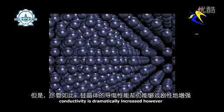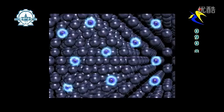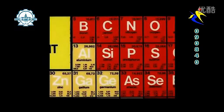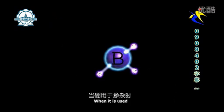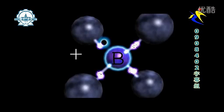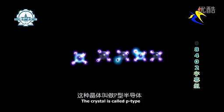Conductivity is dramatically increased, however, when some silicon atoms are replaced with impurities called dopants. In the periodic table, dopants are close to silicon. Boron is a p-type dopant. It has only 3 electrons in its outer shell. When it is used, the missing electron behaves like a positive carrier called a hole. These holes move through the crystal, conducting current in response to applied electric fields. The crystal is called p-type.